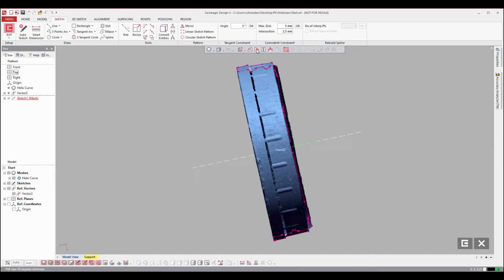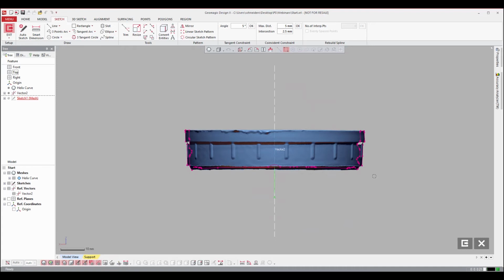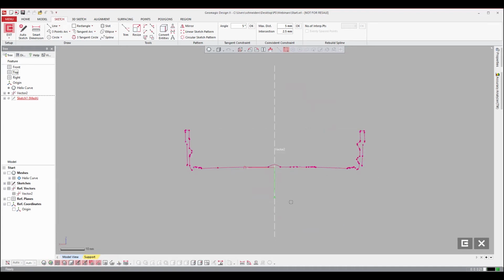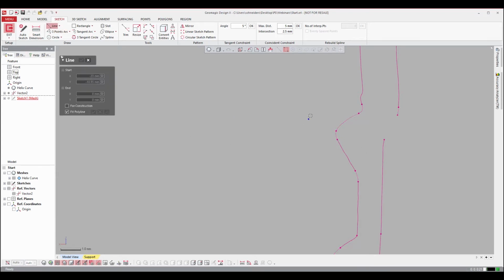We're going to rotate this around and focus on one of these teeth. If we hide our mesh real quick, we can see that our 2D polyline here has two teeth on the right-hand side and then one tooth on the left-hand side. We're going to focus on this top right-hand tooth, because we're going to take this profile and use it in our Helix sketch to revolve it around to create our thread. Taking the line tools here, we're going to fit the top and the bottom of this thread by highlighting the scan information here and extracting those lines.